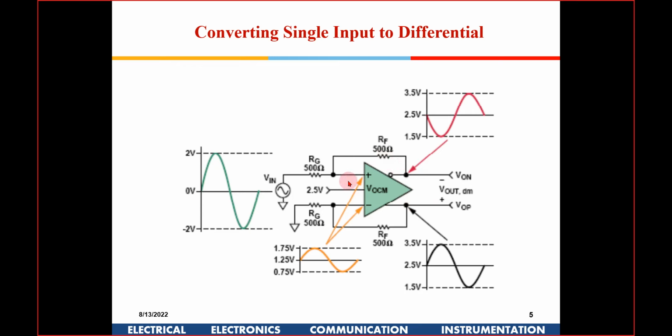This is again just a common method of generating the differential signal. You have a single-ended signal coming here. So this works like an inverting output. Certain op amps will give you both the inverting and the non-inverting output, whereas this bottom path is giving the positive, so you get an in phase component. So you get an out of phase component and you get an in phase component.